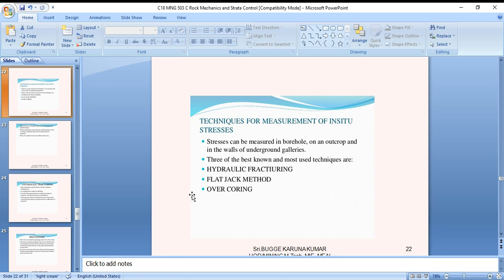These cells are fabricated by forming two identical halves out of malleable sheet metal and brazing or welding the halves together. Copper, brass, or steel has been used for this purpose. Fabricated cells are used in boreholes. The maximum pressure that the cell will withstand depends on a number of factors: the type and thickness of the body, whether the brazing or welding technique. Even more important, it depends on the quality of the grouting, and the care exercised in preventing the formation of voids during installation of the cell.